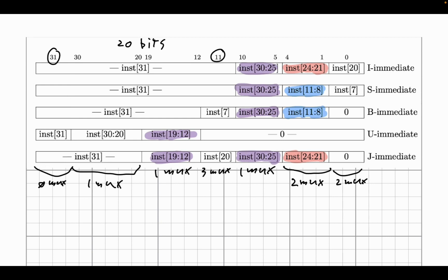So one way that we could reduce the problem of fan out that we get from sign extending this thing is that we could have a very powerful driver transistor that generates a whole lot of current. And we then use that current to make it so that even though there's a lot of capacitance on the wire, it charges up fast and it doesn't actually slow anything down.